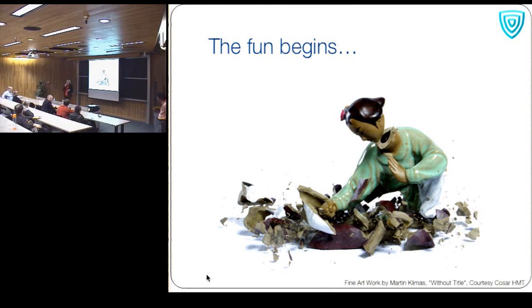So the air entrainment, it's assuming that if we get down to the scale of the regions of cement paste that are between those air entrained pores, that is the mode 1 fracture toughness of that small piece of material. But we didn't have anything better for what a subscale fracture toughness might be. So for lack of better information, we took the macroscale value. But we used cement paste and assumed that the interaction with pores and with other pieces of sand, we're ignoring that.